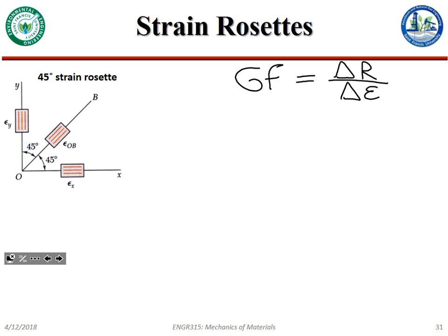And so for a given amount of strain in the material, you get a change in resistance, at least over some range of applicability. Because strains are usually really low, like a couple of percent, if not less, this linear relationship holds decently well.